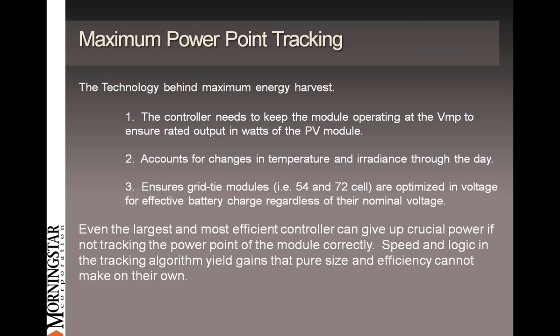Because everyone knows that the dollars per watt on those being the prime manufacturing goal right now, those are handily found in the market and most often at a very efficient price as well. It's important to note that in addition to DC conversion efficiency for a good design on the power electronics side, you've got to be smart too. Even the most efficient controller can give up a lot of power if it's not doing a good job at following the max power point.